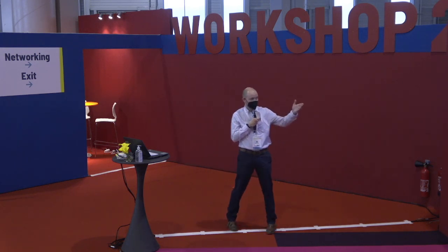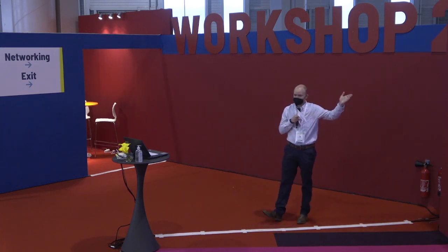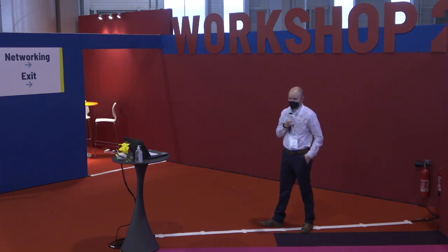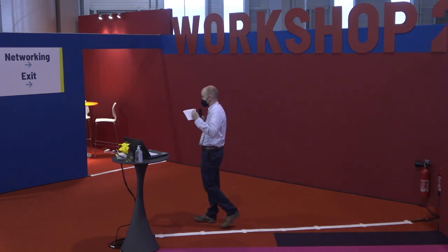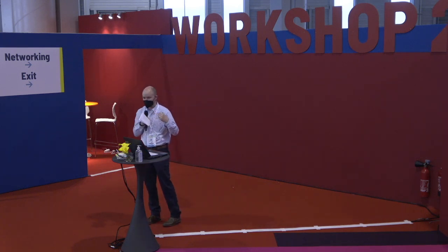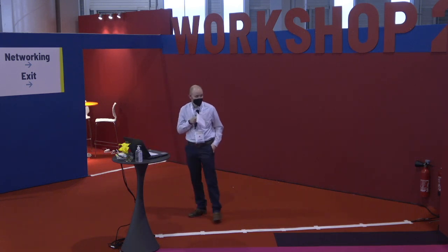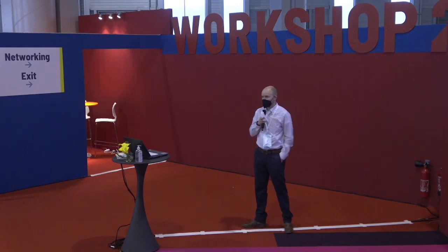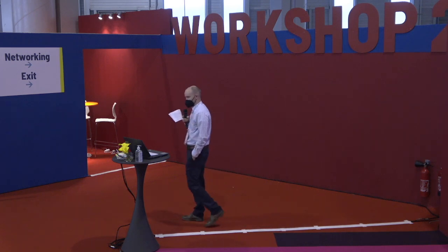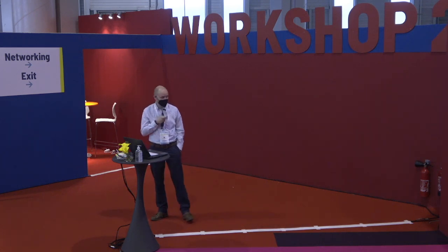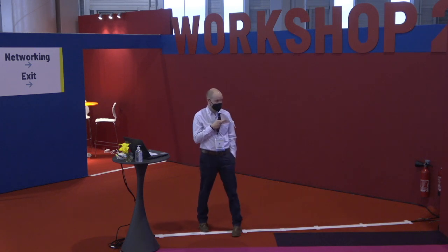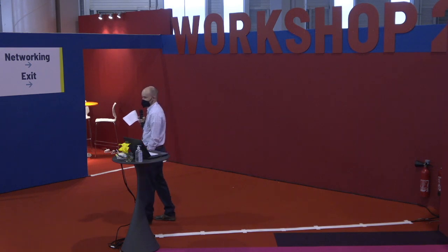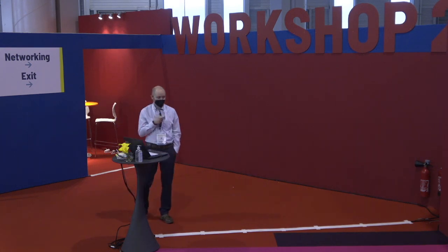When you get into risk 3, you've realized, although it was categorized as safety when they built the plant, based on the analysis, it's of low safety significance. So again, failure does not impact plant safety. It does not increase core damage frequency or large early release frequency. And that is an opportunity to reduce the amount of effort you're spending on that. So for maintenance that you're doing, it doesn't need to be done to the same safety level of maintenance. The testing that you're doing can be reduced. And more importantly, if you're replacing a part, you don't need to replace it with a safety grade part. You can get industrial grade replacements.